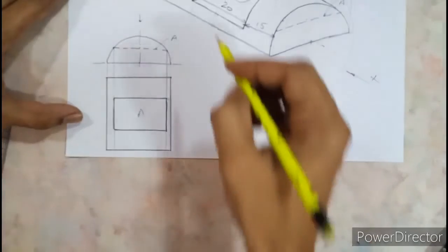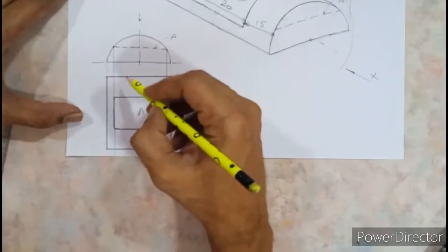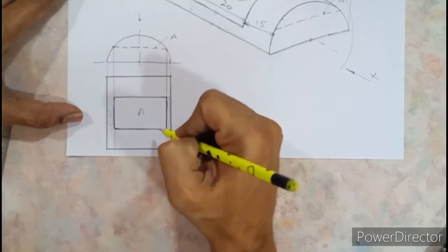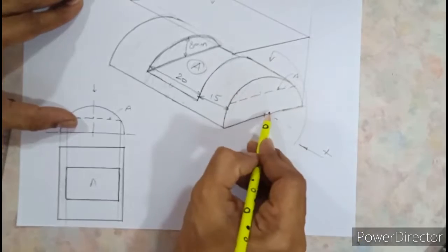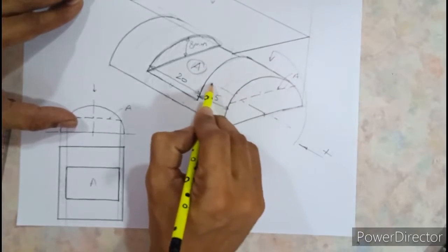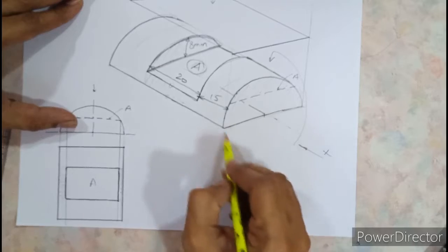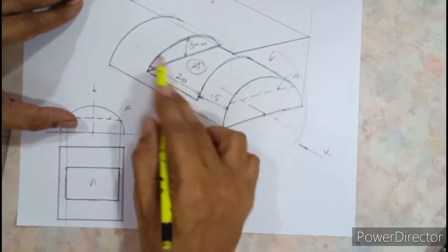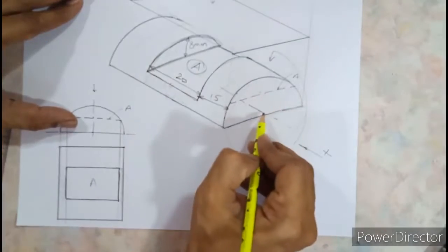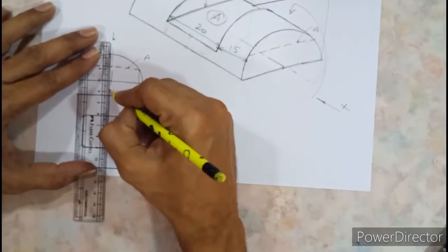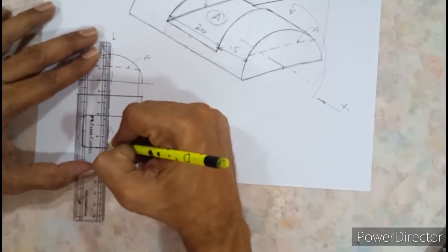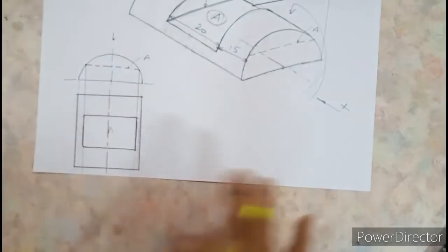Finally, as we discussed before, whenever you draw a rectangle and it is a curved surface, you need to represent an axis line. Try to understand, in this diagram the axis line will move inside, because if this was a full circle, then the axis would have been this one. Now it is a semicircle, so the axis still remains there. Over here we need to show the axis line, big dash and small dash. This represents that it's a curved surface.